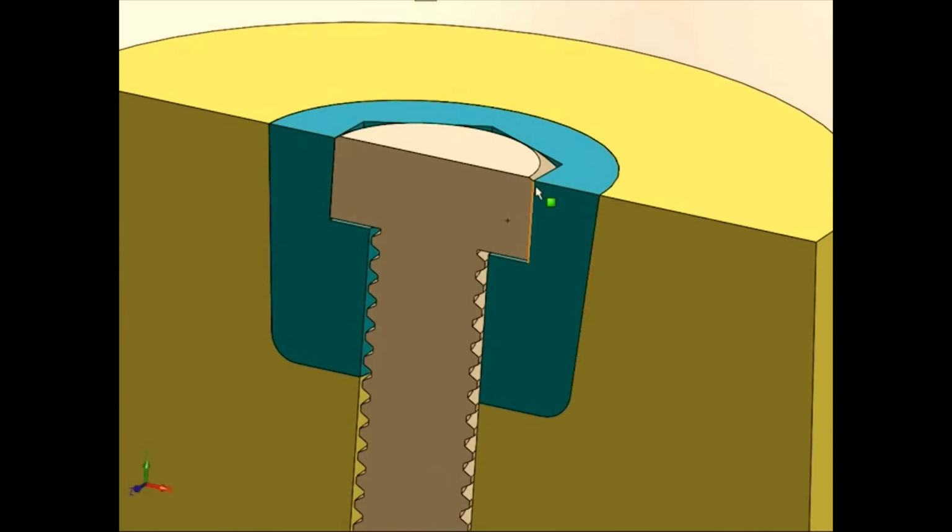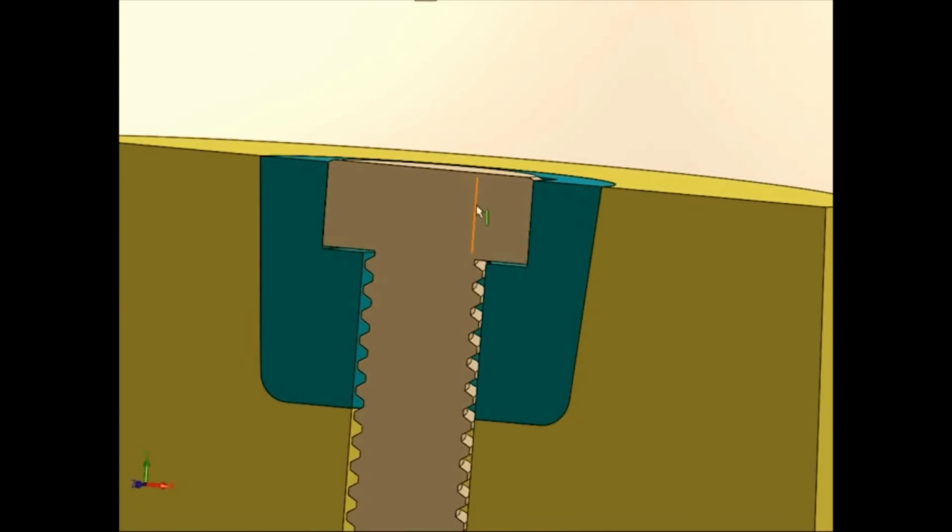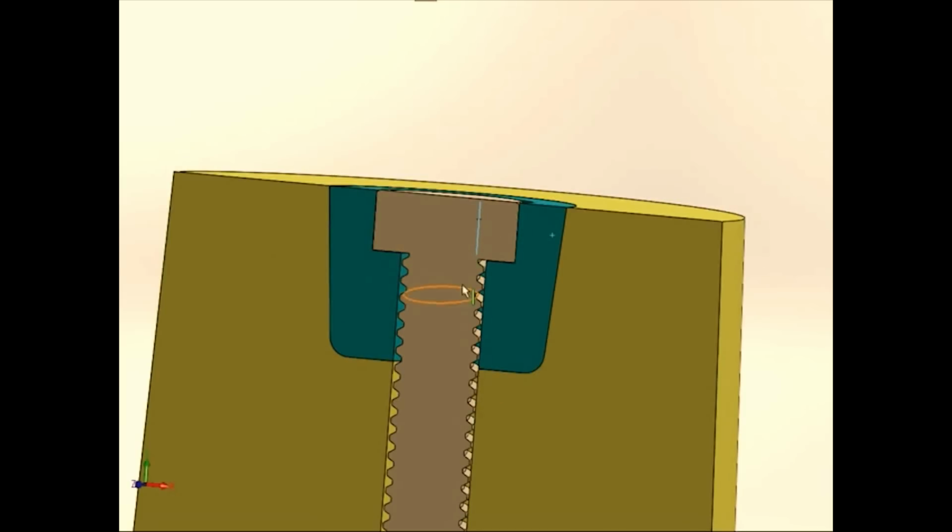We want to make sure that the screw is below the horizon line of the last layer built, or just flush with it. We don't want the head to crash into it because everything's done in layers.